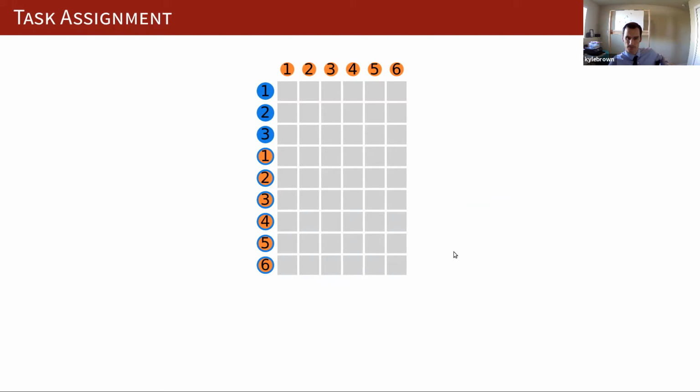The dummy robot's number is the number of the object that was delivered by the robot that just disappeared at that location. So if we put a 1 here, we're assigning dummy robot 3 to task 4. We are saying, in effect, whichever robot just delivered object 3 is now going to be assigned to deliver object 4. So if we put a 1 here, we're assigning robot 2 to task 3, and then dummy robot 3 to task 4, meaning robot 2 first does task 3 and then task 4.